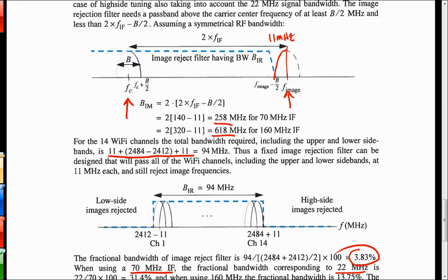I know you do it in the comm lab, but there's a problem when you build a tank circuit with an L and a C in parallel. You don't just have L and C, you've generally got losses in there, so you've got an equivalent shunt resistor across there. And that's due to the loss in the inductor, usually due to the metal loss. And then the capacitor has a dielectric loss as well.